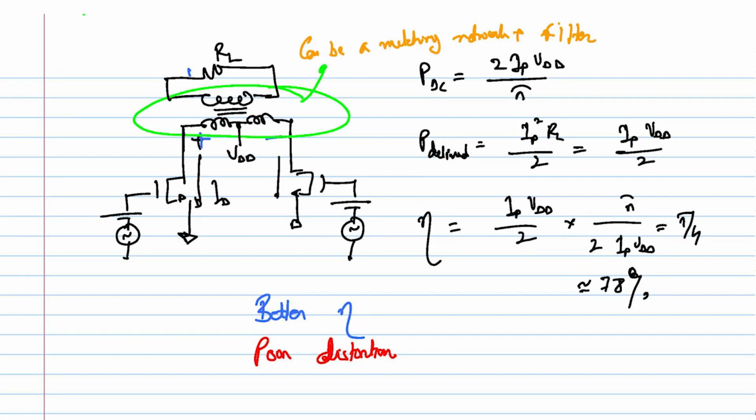So as it turns out, even if you do filtering, in most PAs, when you have a PA, you normally do not put the antenna directly to the PA. I'm assuming you have taken care of the matching network and all. Simply because you are going to have distortion, which means you are going to generate out of band sinusoids, and if you transmit those out of band sinusoids, you are probably going to be transmitting into a band which is not assigned to you.